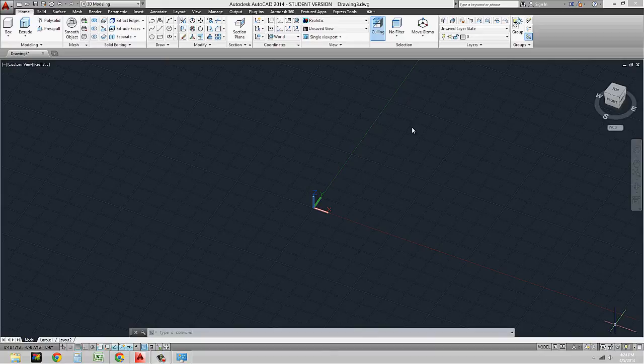When we begin to model in AutoCAD, what I want to note is that you can actually create a model in 3D in two different ways. One is that you can start from scratch, and the other is using existing drawings. By existing drawings, what I mean is that you can XREF a drawing into AutoCAD, and you can use some of the tools in order to extrude some of the solids, some of the walls that are there, or some of the other objects that are there.